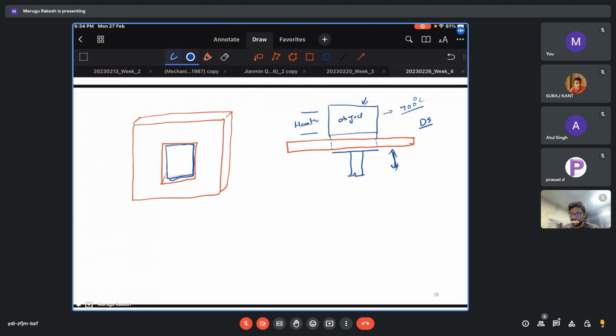So what happens? This is not only in directional solidification. Any setup which is having some tolerances, if there are two objects which have some relative motion, and they have some tolerance, this tolerance should be taken care of, keeping in mind this solid contraction. So many people generally ignore this value. They just use random clearances so that it maintains. So they make sure that even with a good amount of contraction it works.